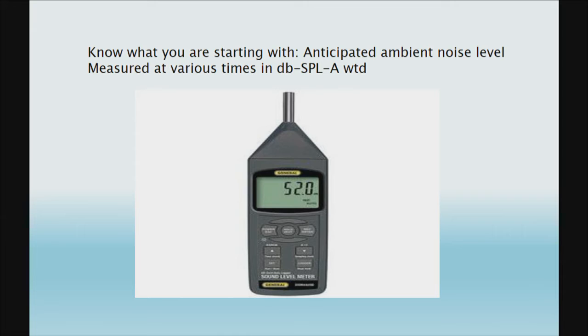They talk in there about some standards like you're putting in a conference room. Maybe we want to be down below 40 dB SPL, A-weighted, or general classroom, we're up here. But going into some of these troubled spaces and doing it at different times. Classes let out. You've got a 1-hour class here and a 2-hour class still in session. What kind of ambient noise, air handling equipment, close to windows and that. So have an idea where you're starting, so when you're designing your system, you know what your starting point is to get that needed SPL level out at the audience's ear.